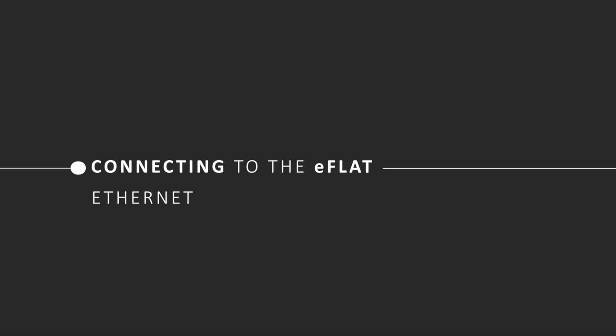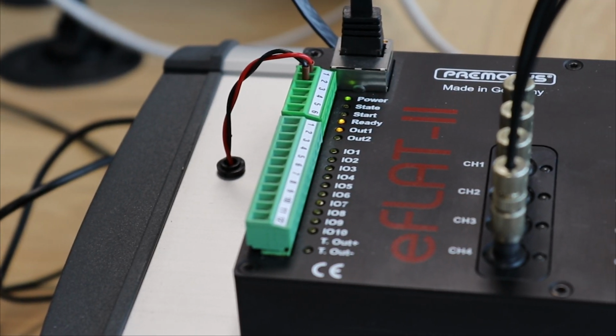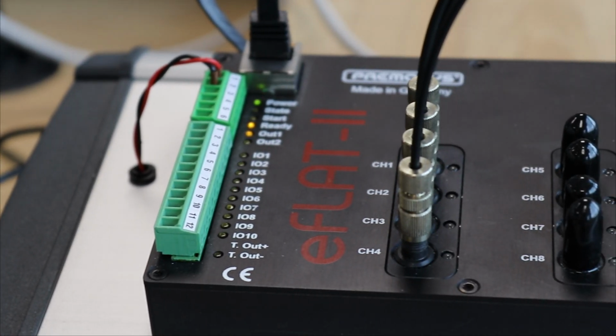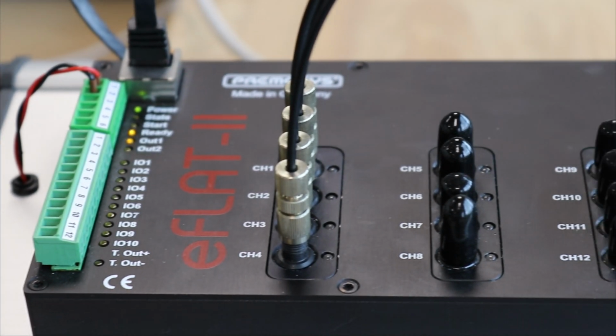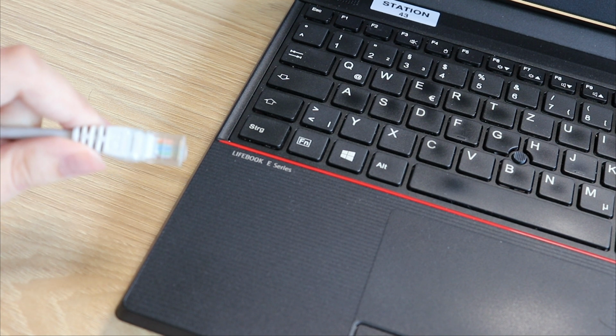In the next step, I will tell you how to connect your eFLAT device with an Ethernet interface. To demonstrate, I will use the eFLAT 2. First, make sure that your interface cable is plugged into your eFLAT device, as well as your laptop or a similar device.